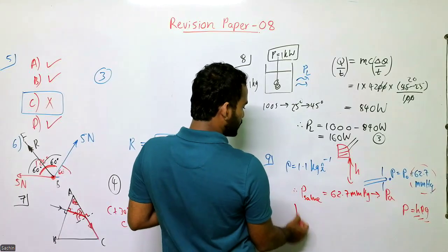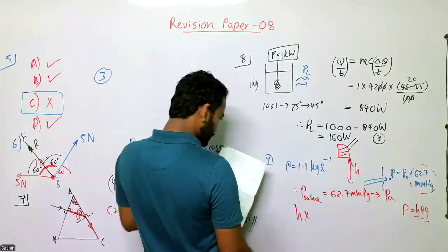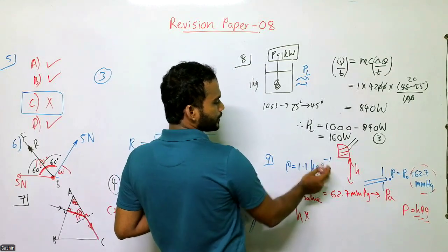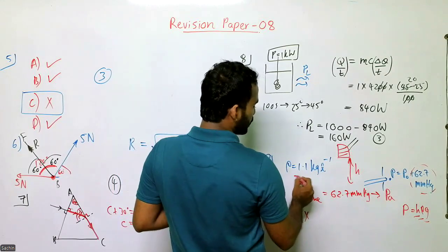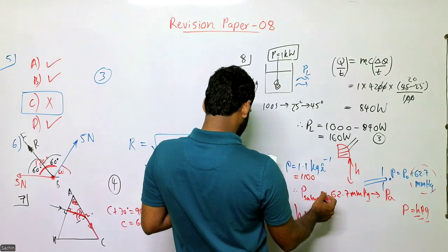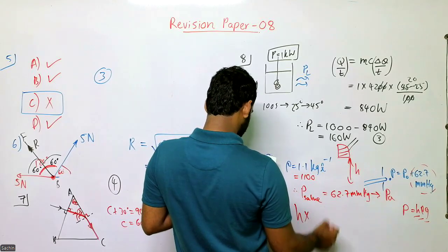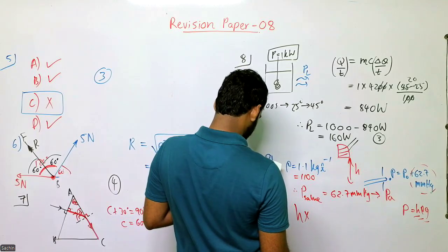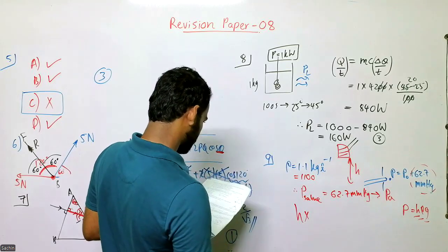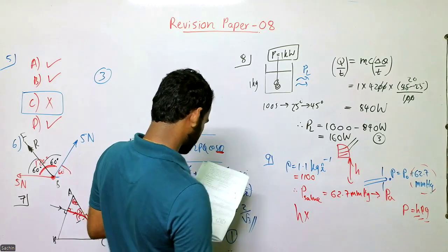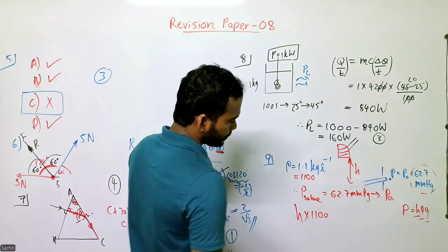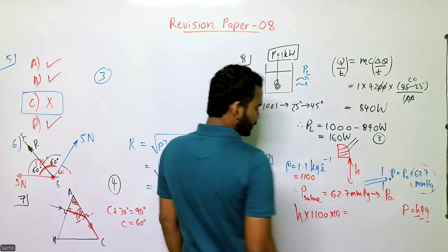The pressure built up by the saline should be equal to the height of the saline bottle times the density of the saline, which is given as 1.1 kilogram per liter. If you convert this value into kilogram per cubic meter, it will be 1100. g is 10.